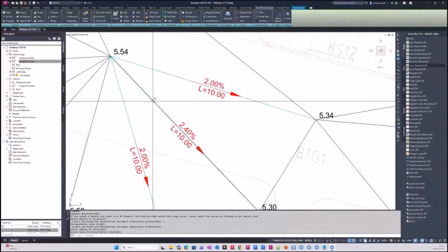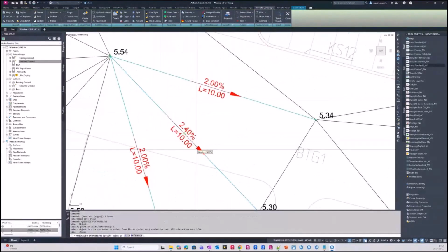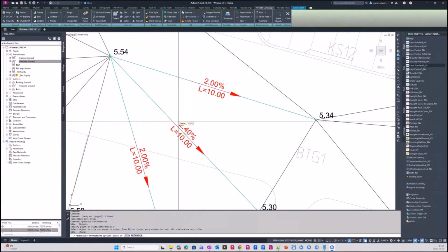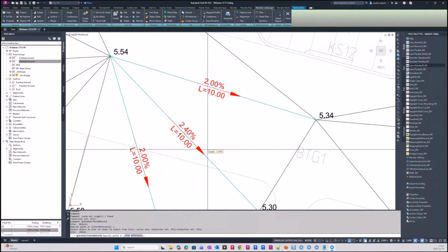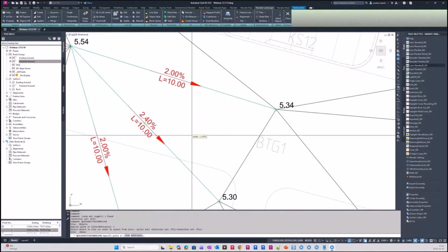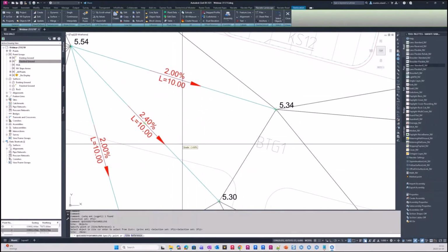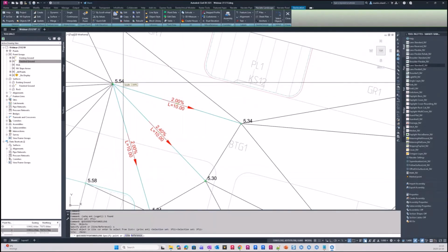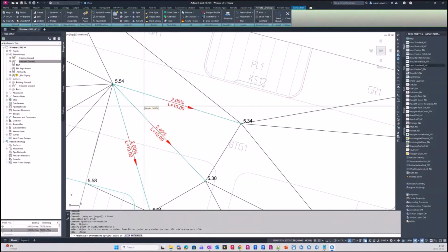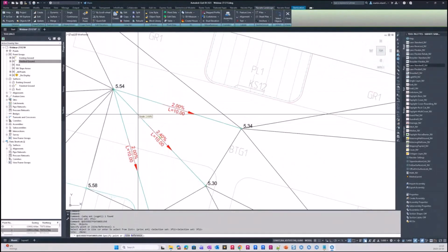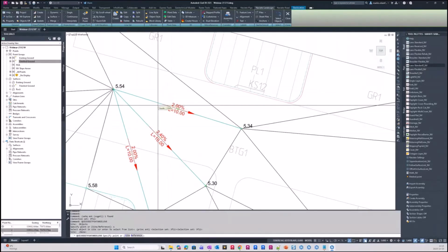And I can also double tap on a line to get this slope function instead. So I can use slope or grade to change it. And it's just a quick elevation editor tool that it accesses. So if there are points to this point, it means that this elevation will stay. And if I have it over the half line, this elevation will change instead. So it's just a quick elevation tool from Civil.